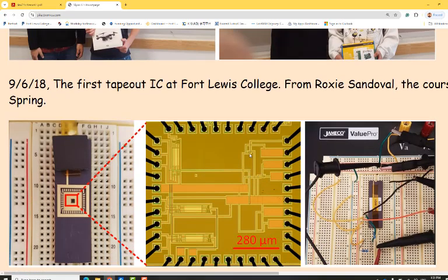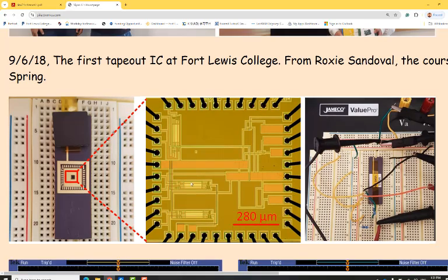I think I still couldn't see it because the wires are way bigger than the chip, in the transistors. So it's just a little tiny thing over here. And that's the op-amp. And this is a 40-year-old technology. 500 nanometer technology. So the smallest the transistor can build on the chip is actually 2 times 500 nano. It's almost 1 micron. So the transistor size is 1 micron. But you can still use somewhere around like 40 transistors to build an op-amp.